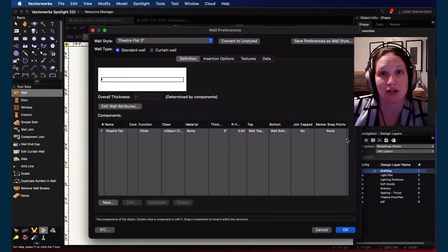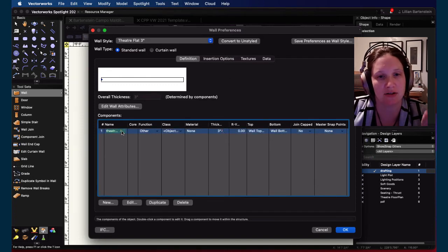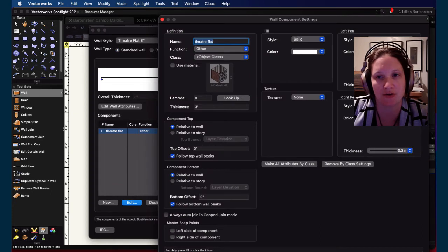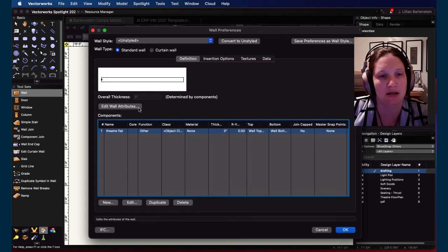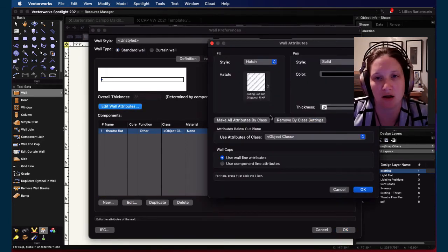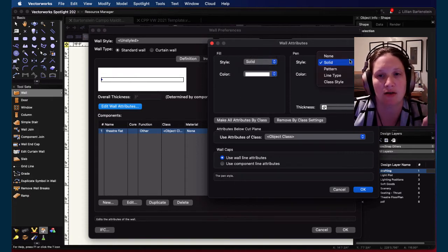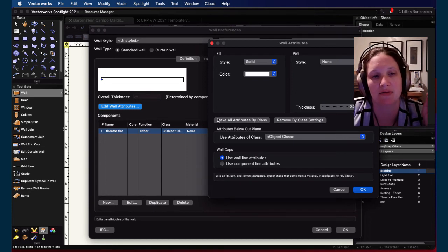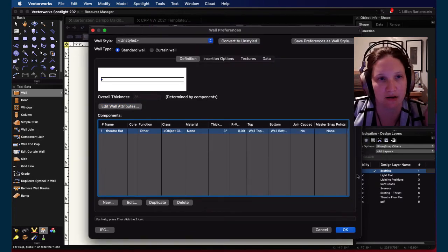That's great. Yo, I just wanted to jump back in and fix one thing that I said incorrectly a moment ago. So I did all of that stuff to give it the one side is heavier than the other, right? So we come in here and edit, and you can see I got a 35 side and a 0.05 side, and it's great. What I haven't done is clear the previous wall attributes. So right now, I want that to be solid, and then I want the overall wall attribute to have no given pen line, and that will mean that that component attribute becomes your pen line for this wall style, okay?